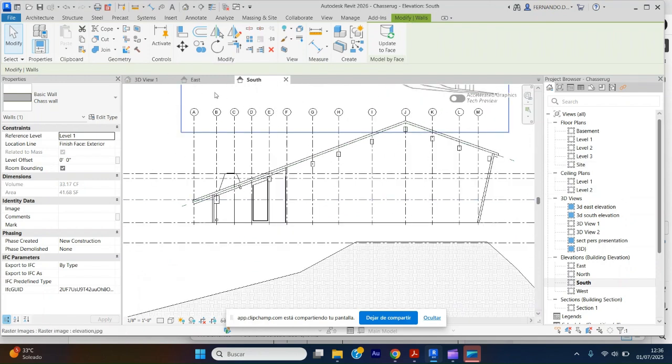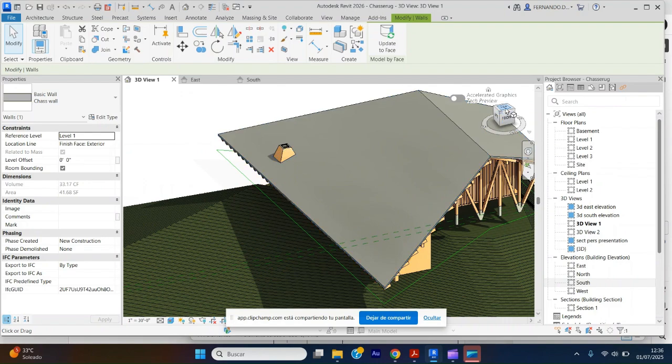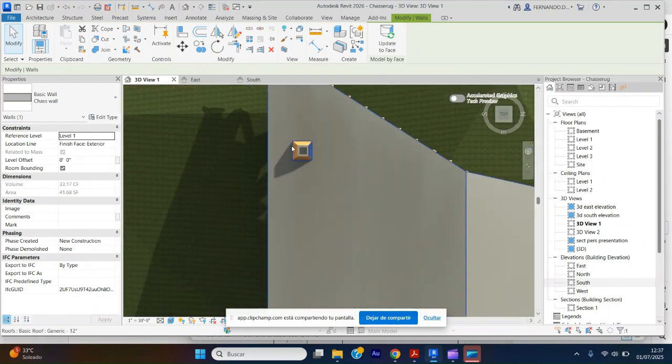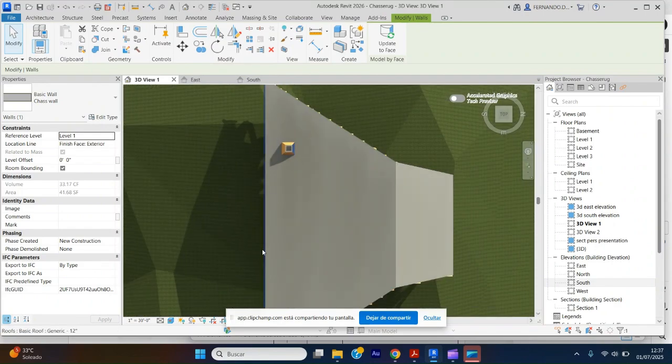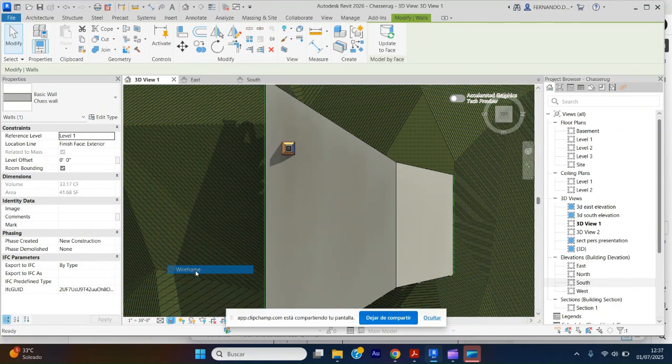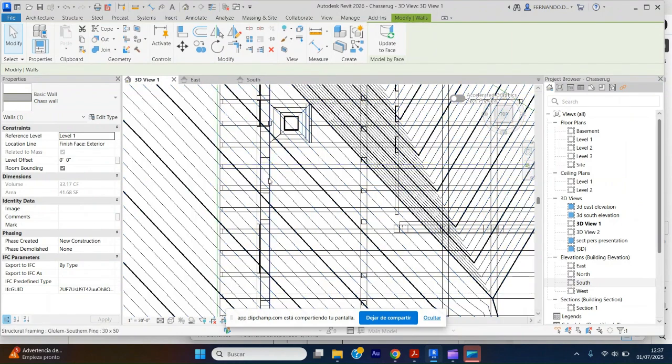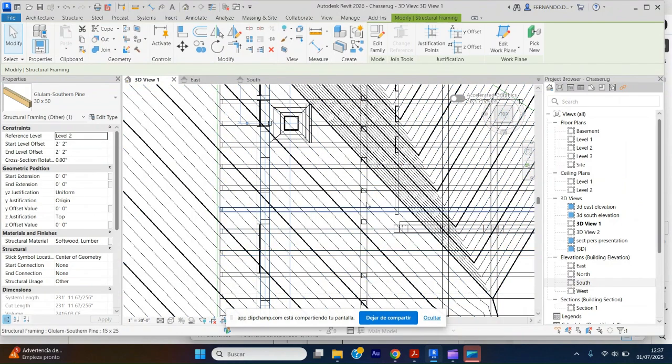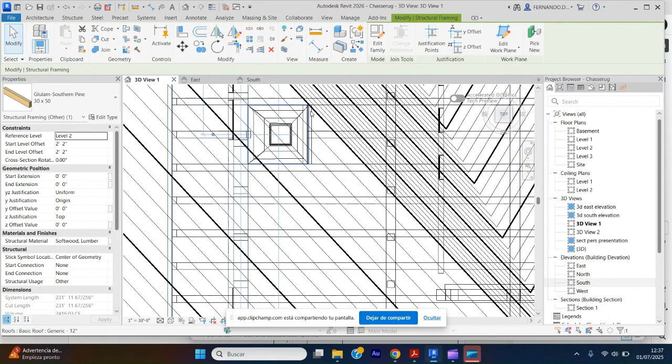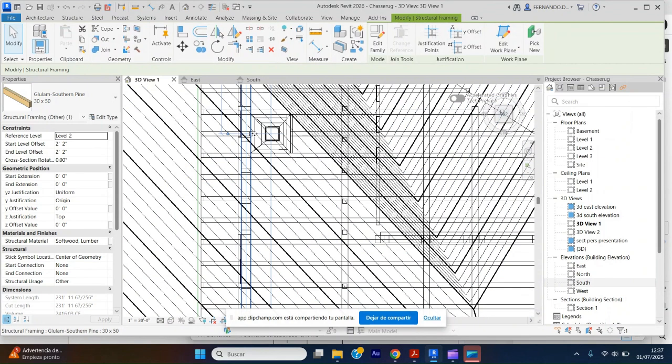Next, we can start with the 3D view, the top view. If we go to the top view, what are the basic guidelines for this? If we go to the wireframe, we need to know that if we have created that beam, this should be the starting point for the pyramid. And the size of this is between two beams of this beam system. We have to make the most of the existing structure, because opening a hole in the roof means that we have to create elements so that we have a solid or rigid frame around the skylight.